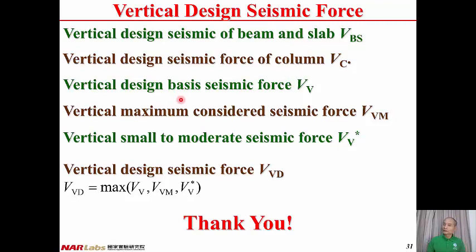We can determine the vertical design basis seismic force VV and also the vertical maximum considered seismic force VVM and the vertical small to moderate seismic force VV star by similar procedures. Once we have these three seismic forces, we pick up the maximum and assign it to be the vertical design seismic force. Therefore, the vertical design seismic force VVD is the maximum of VV, VVM, and VV star.